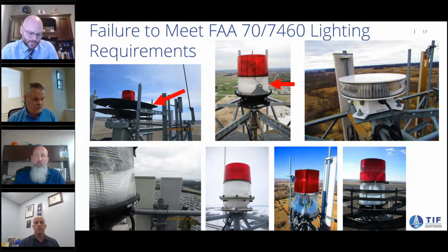Yeah, that's the critical part, and I want to stress what John said there. Do not take the onus on yourself to just change it. There are height regulations, there are lighting regulations that we do have to follow, and if you just go ahead and raise the beacon and put them over their height limit, you've caused one problem trying to fix a different problem. Yeah. And then sometimes the RF engineers are okay with you dropping a foot or two. It won't mess up too much. So again, that's where everyone has to come together: end user, tower structure owner, GC. We all meet and provide the best solution.